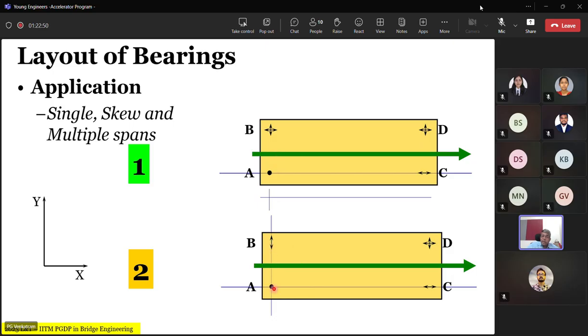in the arrangement 2, all the transverse seismic forces go on A. A and C also, correct. So the question is, there is another phenomenon that comes in: when you have any longitudinal force which is acting at the CG and you have a support reaction here, there's an overall transverse bending moment which will lead to additional lateral loads coming into the fixed bearing.